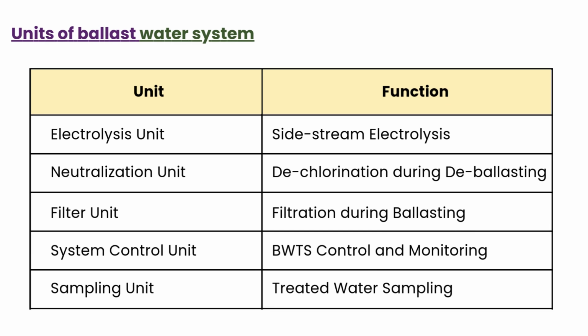Electrolysis unit, and its function is side stream electrolysis. Neutralization unit, dechlorination during deballasting. Filter unit, filtration during ballasting. System control unit, ballast water treatment system controls and monitoring. Sampling unit is treated water sampling.